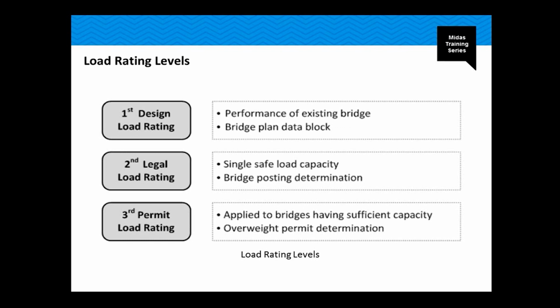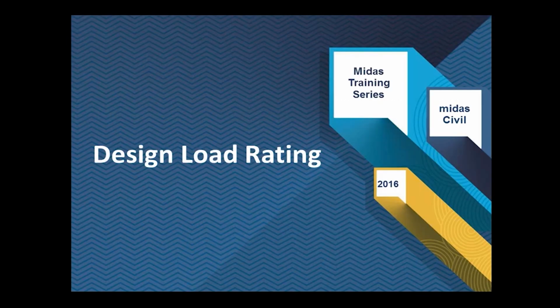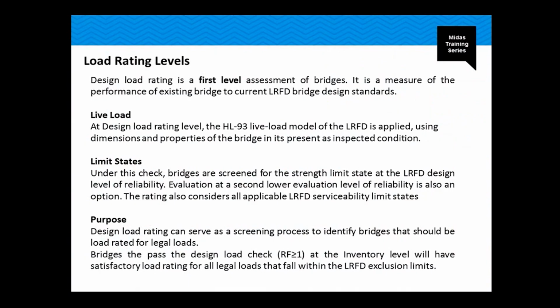The second, legal load rating, is a single safe load capacity and is used to determine the bridge posting. And the third level is the permit load rating, and it is applied to bridges having sufficient capacity, and also it is used to determine the overweight permit. So here are the three levels, and we're gonna go and define each one of them. The design load rating is the first level assessment of bridges.